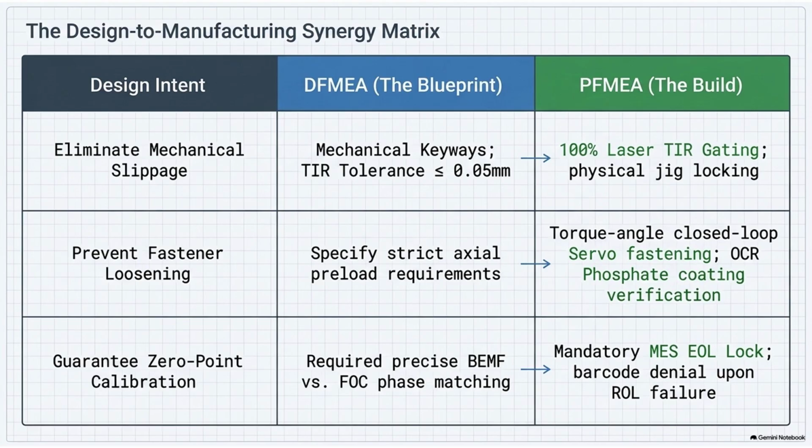So the factory mandates phosphate-coated screws. The phosphate coating acts as a standardized microlubricant. It locks in the K-factor. It ensures that 100% of the screwdriver's torque energy is converted directly into true downward axial clamping force. It removes the unpredictable friction variable entirely.